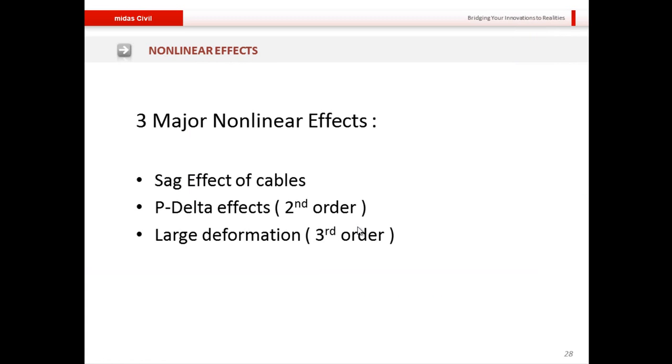Now let's discuss nonlinear effects. There are three major nonlinear effects to be considered in cable bridges. First is the sag effect of cables. The second is the P delta effect or the second order effect, and the third being large deformation or third order effects.